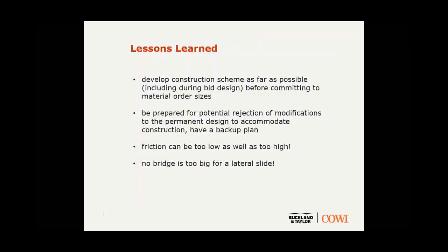A few lessons learned, since that's part of the process here. Try to develop construction schemes as far as you can, especially during bid design, before you have to commit to material order sizes. This is particularly an issue in design-build, where material orders go in very early and you don't have much chance to change them as you develop your construction scheme.